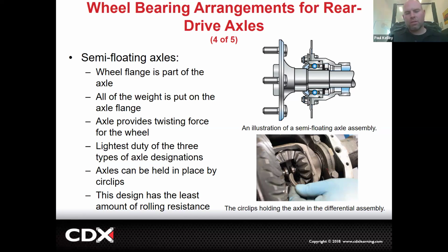When you go to pull these out, though, they're pretty easy. There is no setup on that bearing. It just slides into the bearing. That's it. You have to take some brake stuff apart, push the axle inward, and then see the C clip. We're pulling the C clip out and then the axle will slide out. But to pull the C clip out, you have to unbolt and pull this pin out. Then the axle will slide in enough to get the C clip out, grab it with a magnet or something, and then slide the axle out.